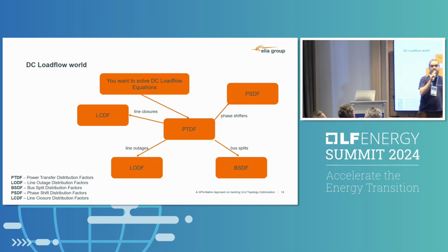This is actually a key component. This has been invented in 2023, so a year and a bit ago. People at TenneT, credits to Joost van Dijk and Jan Viebahn and co, came up with the math for how to do a similar idea like the LODF. Basically, the LODF is you remove a line, and apply this to couplers. A coupler you could see as a line with infinite admittance. Now removing something with infinite admittance makes you divide by 0, so it's a little bit tricky to actually do that. But the math eventually came out, and you can do a rank 1 update with the BSDF.